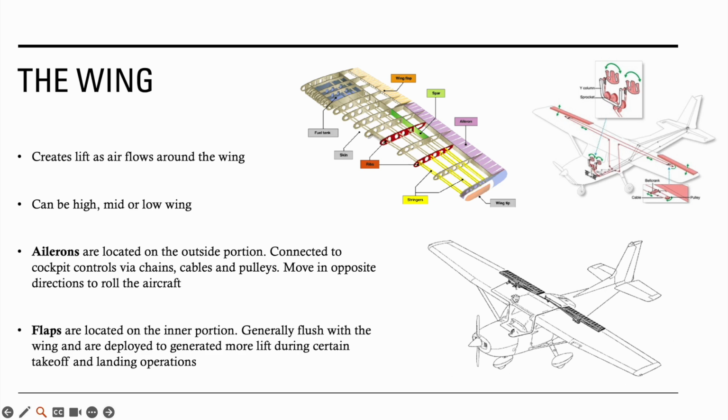So there's only one motor, it's in the right wing. You don't want isolated flap motors, because if one fails and you have one flap that's being deployed and the other one stays up, it's not very good for stability. So if your flaps fail, you want both of them to fail together.